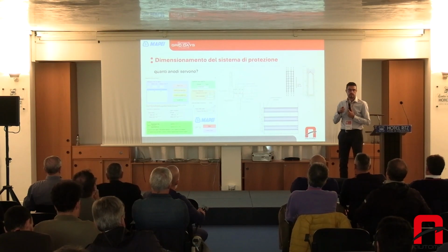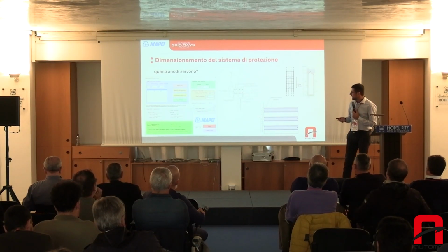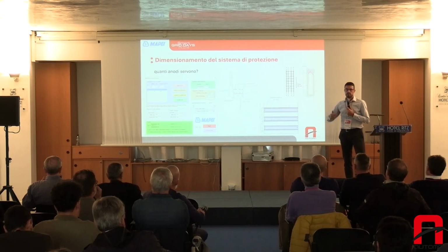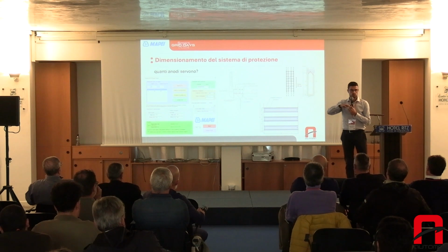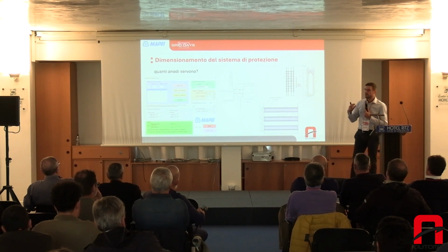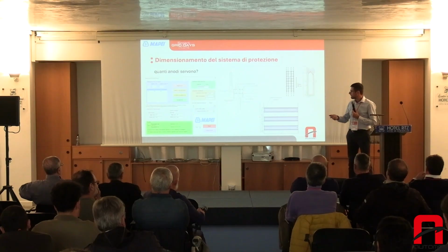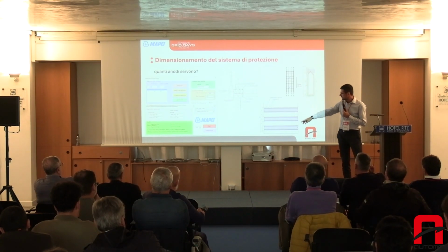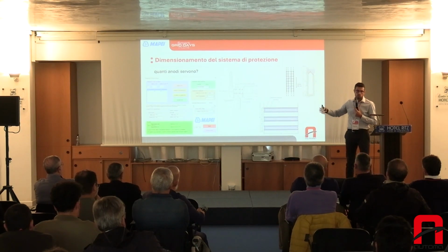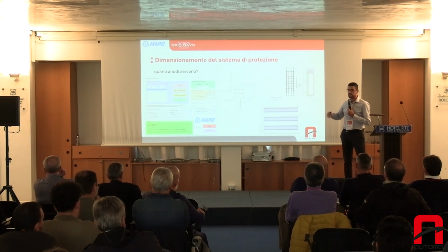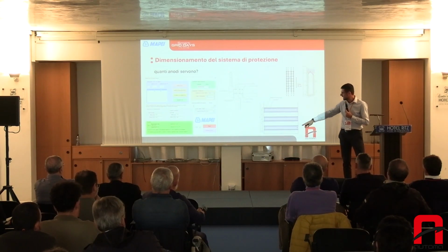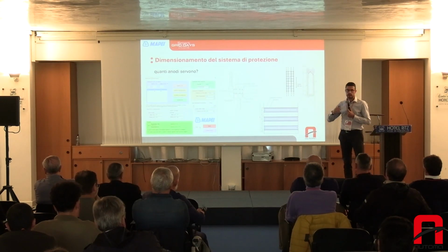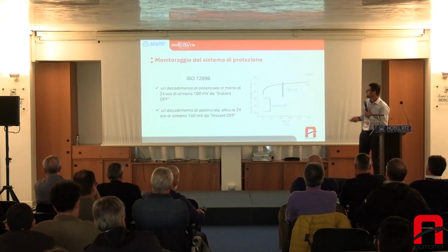The number of anodes and the amount depends also on the reinforcement that's present in the structure. Here you see, in the previous example, we had a continuity of sheets. If the density of the reinforced elements is lower, then you can place the sheets with some spacing between them. In this case, generally, you need to use one or at least two electrical connections per sheet, so that you have a better guarantee of connection between anode and cathode.